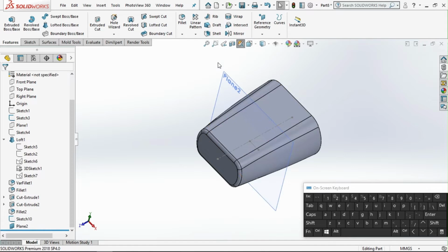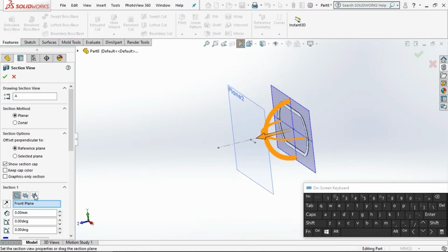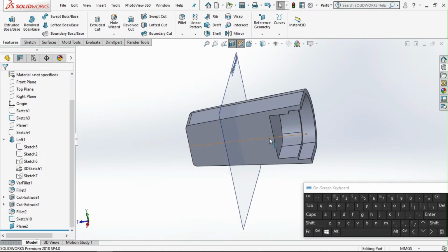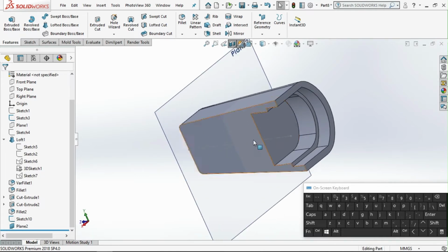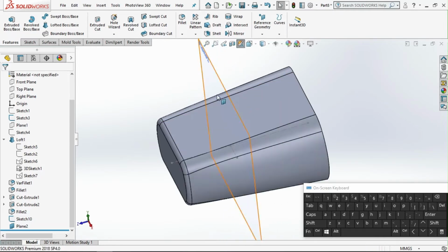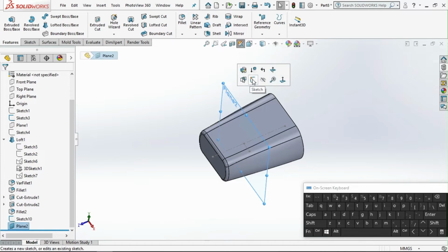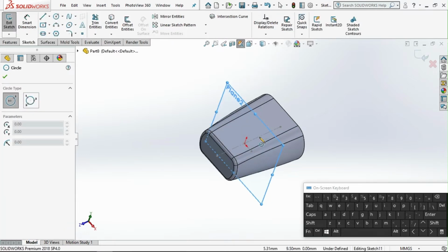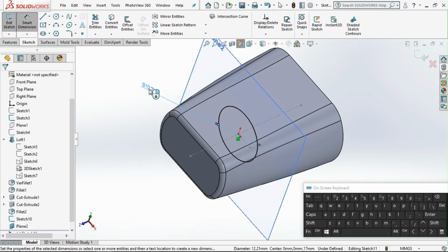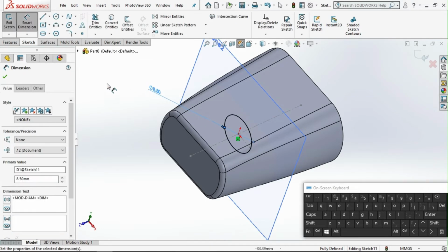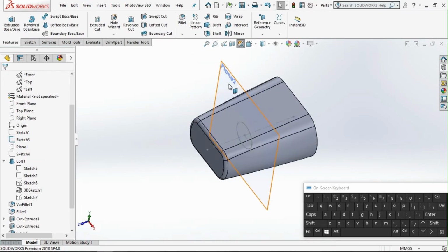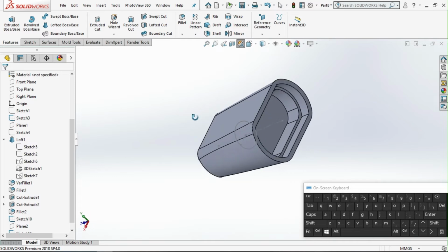As you know, inside here is solid. What the loft cut does is we want to remove this solid part into a profile. Later we will do the profile. Okay. At plane 2, we sketch a circle with the diameter 8.5. 8.5. Enter. Okay. In this plane, I can hide it already.